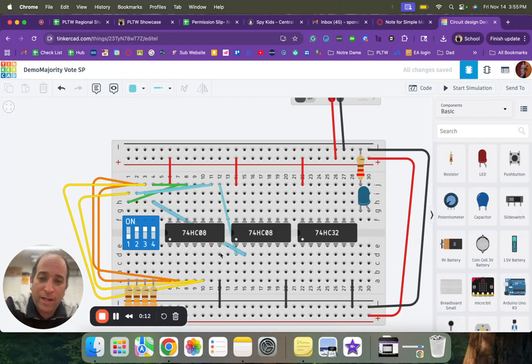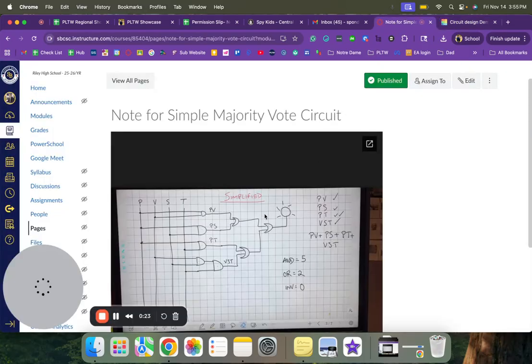We've got all of our AND gates plugged in. Now we're just taking it to the OR gates. Going to continue to try and color code them so that you can see what matches what, and just checking off of our notes. We've got all of the AND gates done, and we only need 3 OR gates.